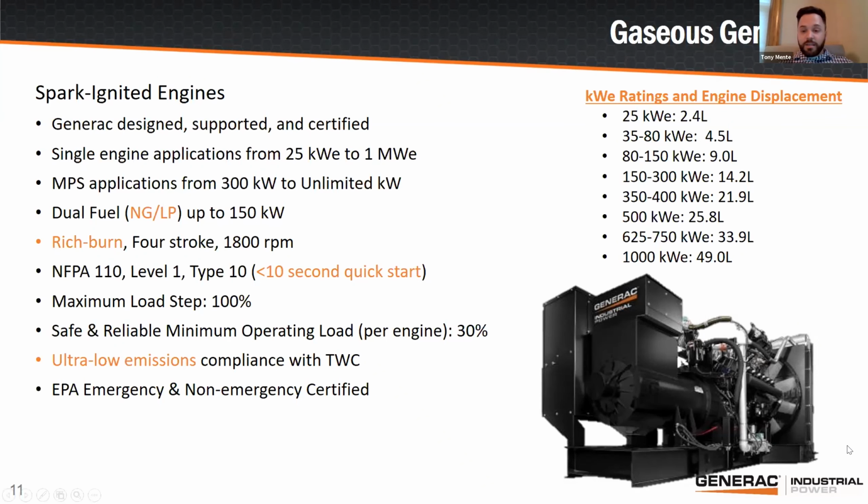These generators can take 100% load step. That's some of the nomenclature people stick to with diesels: you can throw a bunch of load at them, and you can't do that with gas. Well, you can do that with our gas engines. They can take 100% load step just like a diesel. But on the flip side, we're also able to operate the machines at very light loads. So if you had a certain period of time where you needed to run the generator at 25%, it's okay. You don't have to worry about wet stacking or other things that you might have to with a diesel.